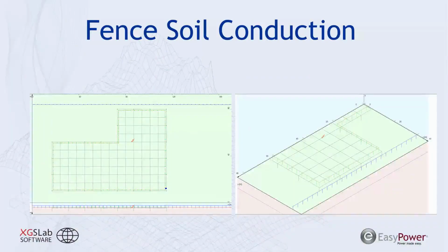A more challenging situation with a neighbor fence is when we start to see touch voltage hazards that develop through the conduction through soil. So we have the same station here. I've elevated the fault current or the energization, and we have that neighbor fence not directly connected to our substation fence anymore, but it's approximately 20 feet outside the station.